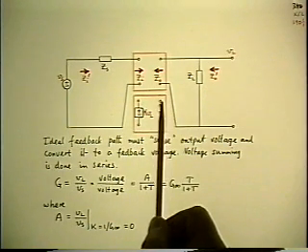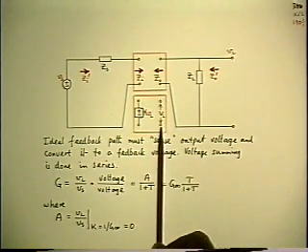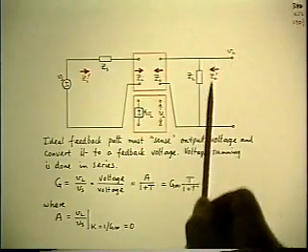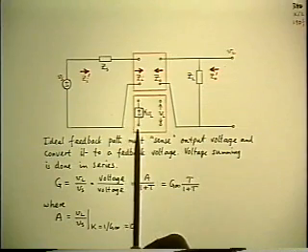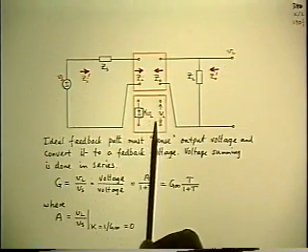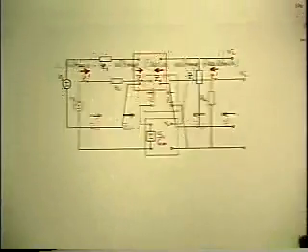So that tells you right away how you have to connect this feedback path. You've got to connect it so that the voltage between the two input terminals of the feedback box is the same as the output voltage. So obviously you have to connect it in parallel with the output. And at the other end, the fed-back signal is a voltage, and you have to do voltage differencing with the input. And the way you do voltage differencing is by connecting in series opposition. So that tells you how you have to connect the feedback path at each end.